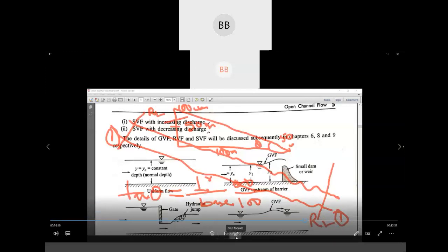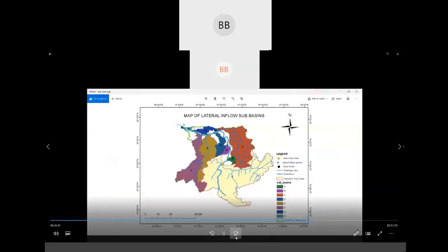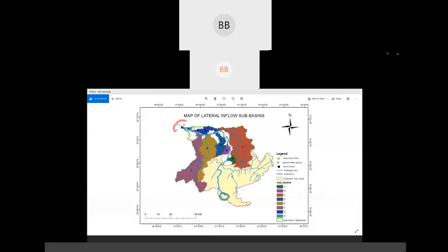So we find out two slopes. One is the slope of the whole channel. Means what the elevation is here at the upstream, and what elevation is in the downstream. Then we have taken two elevations, and you cannot take the vertical distance. You have to take the whole length of the river. So that will give you appropriate, or you can say not accurate, almost accurate values.